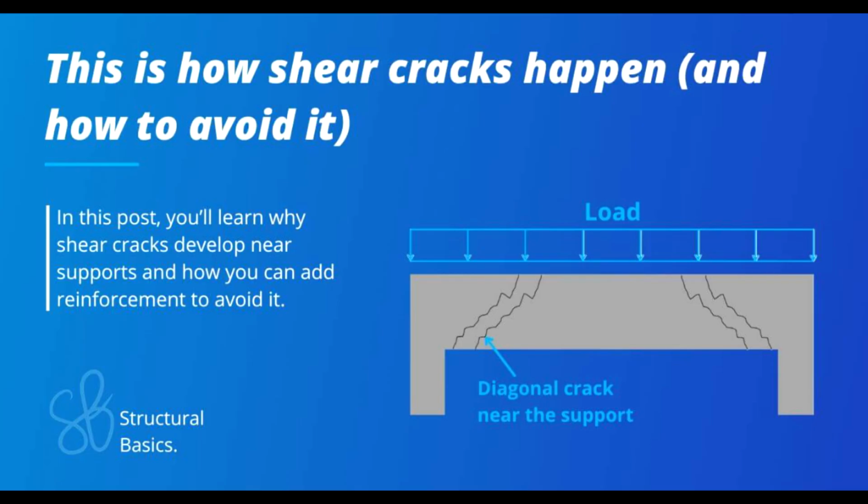And it's shocking to me how many engineers I've worked with are unaware of the basic fundamentals of shear in reinforced concrete structures. In this short article, I'll give an introduction to the most important basics, at least to me, of shear, why shear cracks happen and how we add shear reinforcement, so that, hopefully, RC elements don't fail in shear. Why and how do shear cracks develop in reinforced concrete beams?